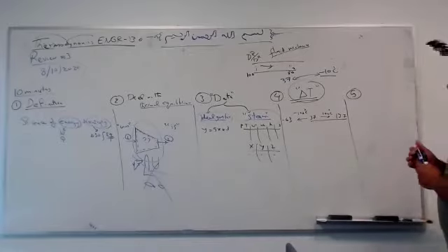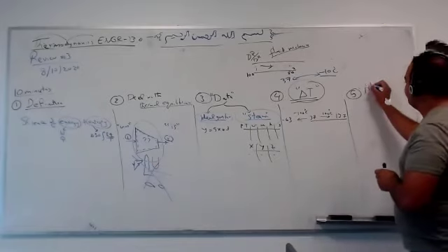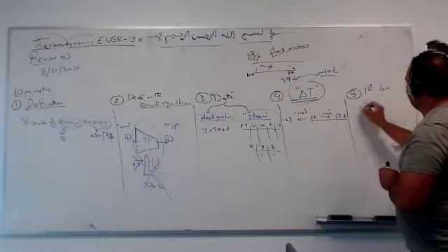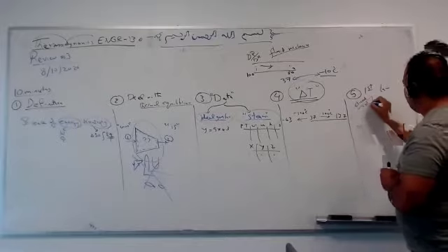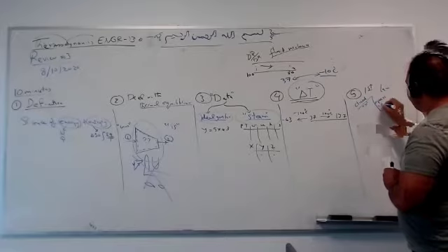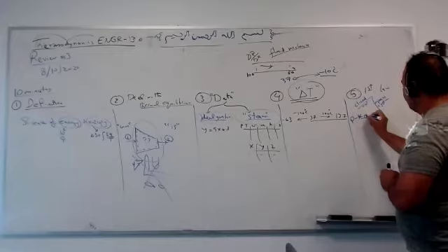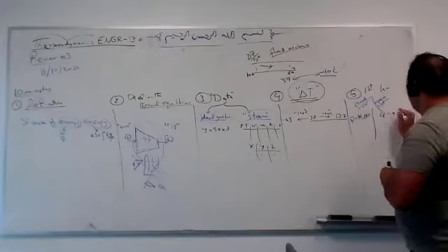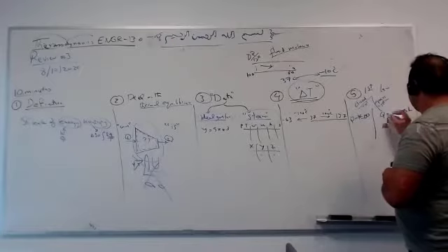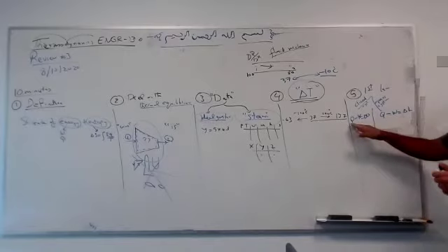For example, last but not least, is the first law. We have two first laws: closed system and open system. Closed is Q minus W equals delta U. This is the very general one. Q minus W equals delta H is a simplified version, neglecting the kinetic energy and potential energy. So for a closed system, Q minus W equals delta U.